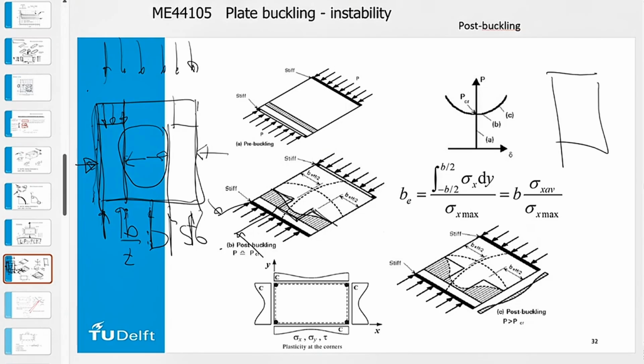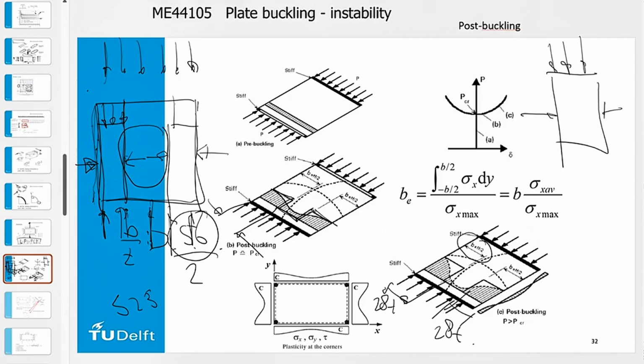So if I assume that the buckling limit and the yield limit are the same, then the width I have, that is my effective width. So the effective width divided by 2. So this 56, which is from S235, divided by 2, is then 28. So 28 times the thickness here and 28 times the thickness there. There we can go up to the yield limit. Even if the plate is wider, I still have at the edge these reserve capacities left.